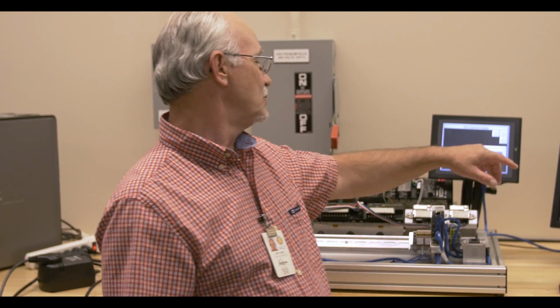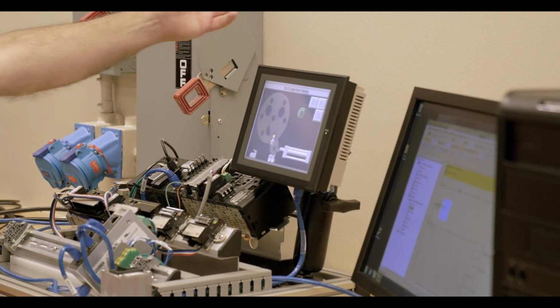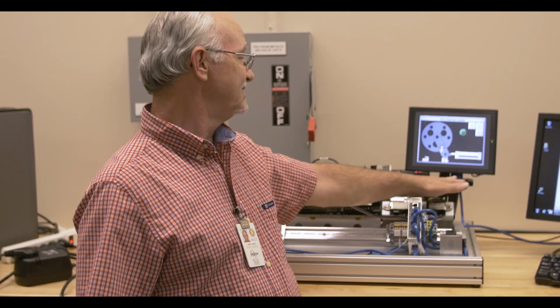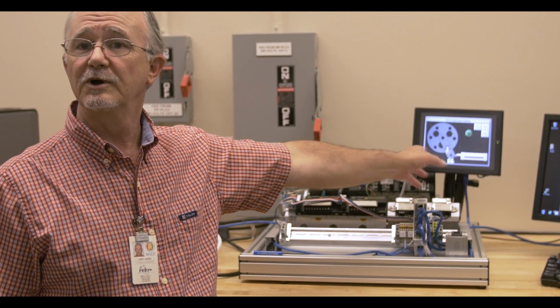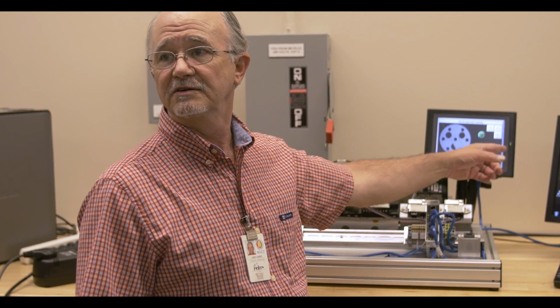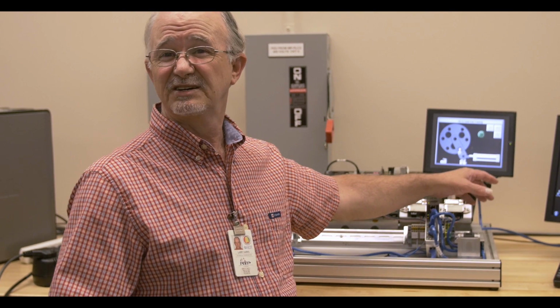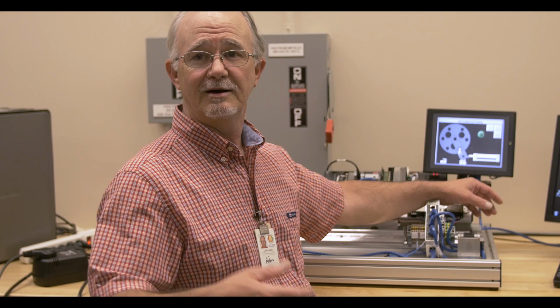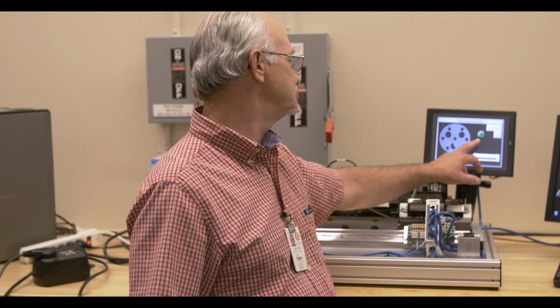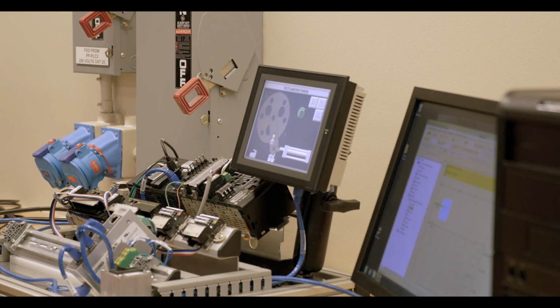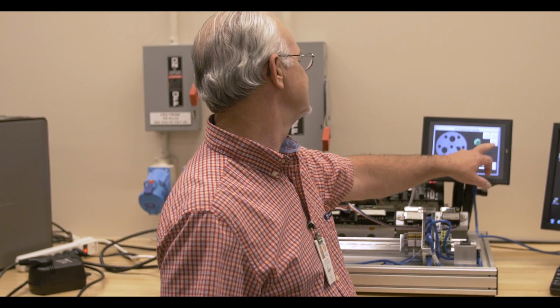Once it turns off power to the cylinder, then the cylinder will fully retract. We start at that point, we move through our HMI programs. This is basically a cylinder that we're going to use to increment a conveyor a set distance every time the cylinder is actuated. It's basically the same thing. I've got inputs, outputs, the same basic logic structure. So that gives you a little idea of the next step in the process.